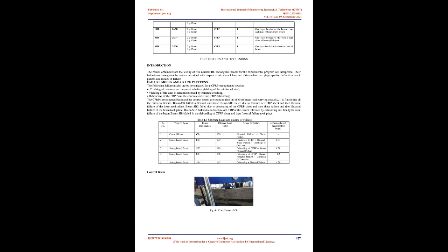Detailing of reinforcement in RC beams. For all the 5 reinforced concrete beams the same arrangement of reinforcement will be made. The tension reinforcement consists of 2 numbers of 16 mm and 1 number of 12 mm HYSD bars shown in Figure 3.1. FRP. Fiber reinforced polymer, FRP, composites comprise fibers of high tensile strength within a polymer matrix such as